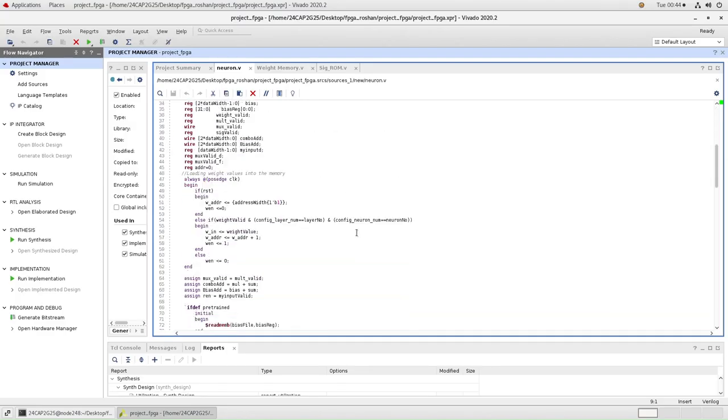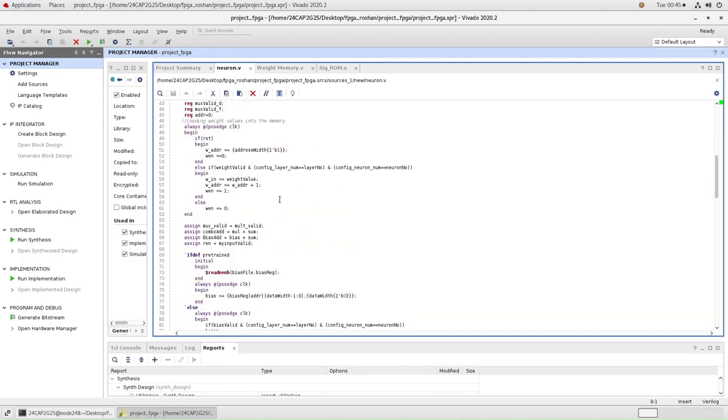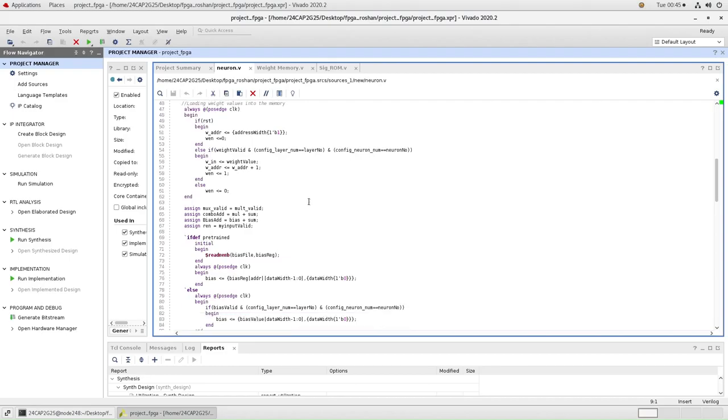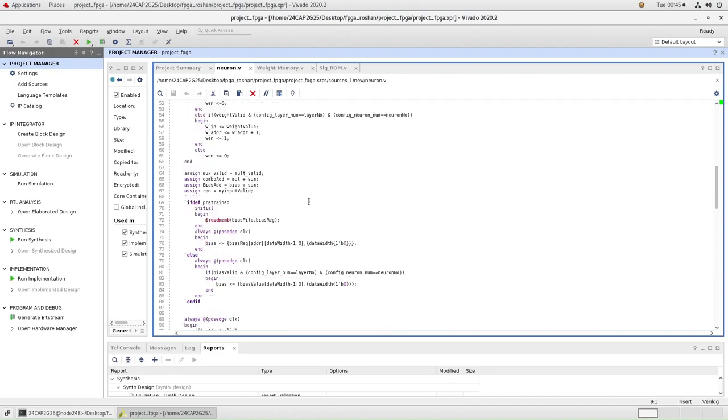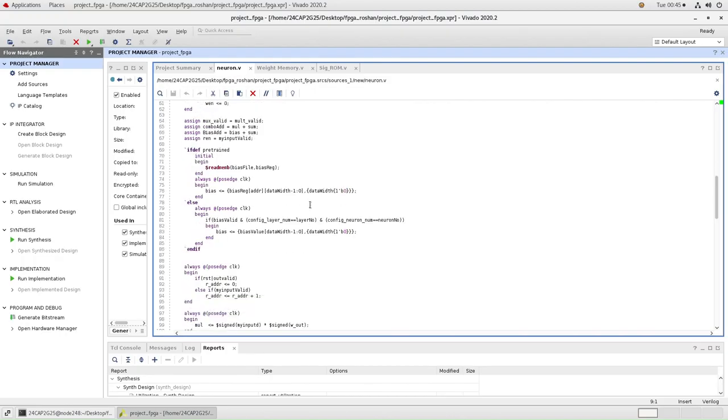The main operation performed by this module is memory management. When weight and bias data are valid, they are written into memory. Input data is read from memory based on the read address. The module does the computation such as MAC, bias addition, and activation function. Control signals such as the memory write address and read address facilitate memory read and write operations.